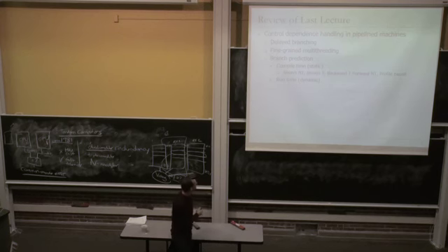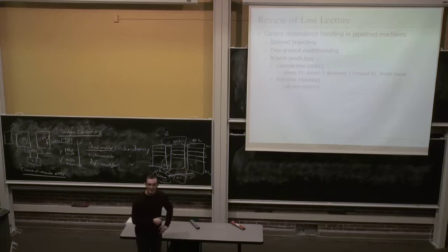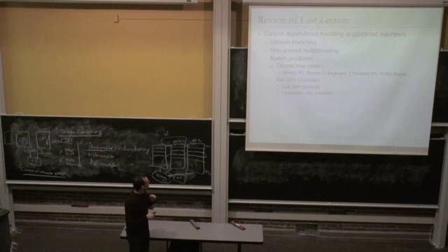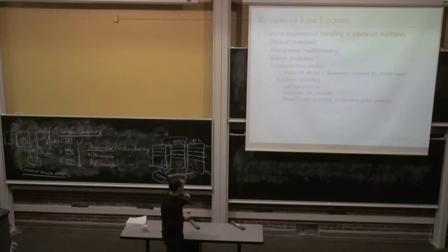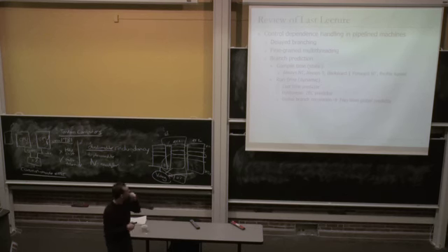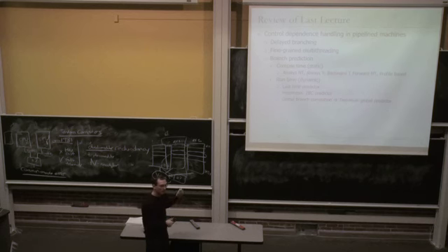And we talked about dynamic branch prediction. We talked about the last time predictor. We added hysteresis to it because we didn't want to change our opinion based on a single inconsistent outcome, if you will. Then we talked about global branch correlation. We talked about the concept that the outcomes of different branches are correlated with each other because of the code constructs. And we designed a two-level global predictor.